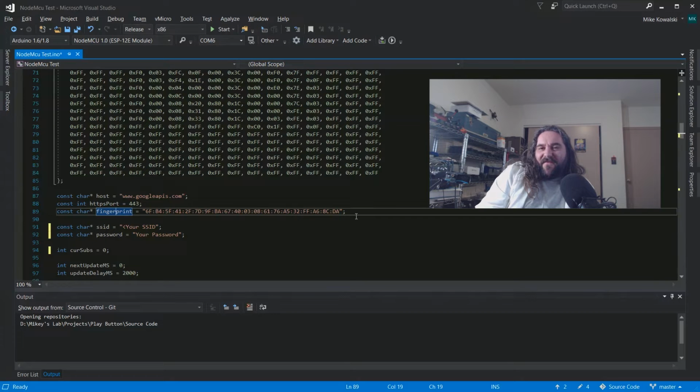What an SSL certificate is, it's somebody on the internet telling you that the server that you're communicating with is the server you think it is. Now, usually this is a trusted facility that says, yes, I know that this is Google. I've dealt with them. It's definitely Google's server, right? You can trust them. But what comes back then is the certificate ID. Now, dealing with certificates on a microcontroller or something as weak as an ESP8266 is going to be a pain. There's just not enough processing power to do it properly. So we take the fingerprint and we compare it and we vouch the server that way.